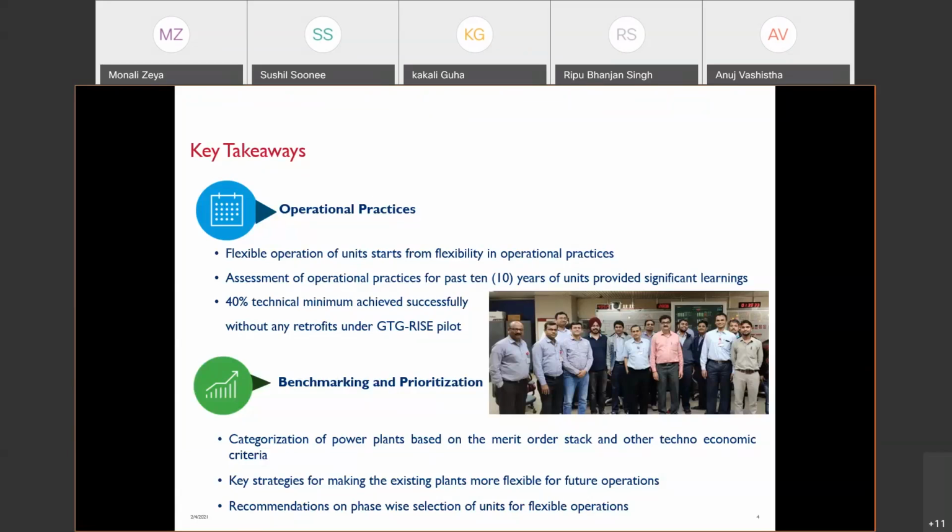So if I talk about numbers, the Central Electricity Authority, the nodal agency in India, has forecasted a scenario for, let's say, July 2022, a worst case scenario where 160 gigawatts of solar penetrate the grid, and we have close to 82 gigawatts of conventional coal-based capacity ramping down in a single day, and the rate at which it is going to ramp up and ramp down is close to 300 to 310 megawatts per minute.